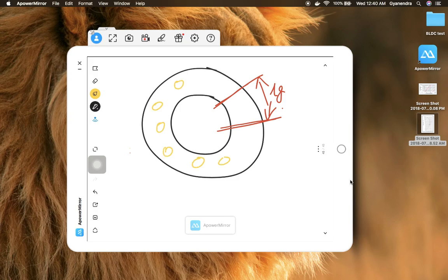The whole air gap is distributed throughout the core. How it's done is that non-magnetic materials are used inside the core, throughout the core, so that we get the suitable reluctance required for meeting the inductance specification.